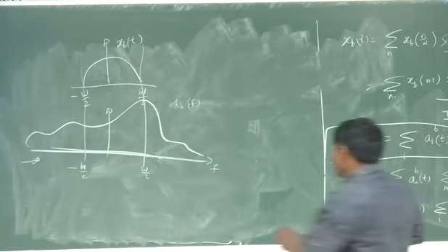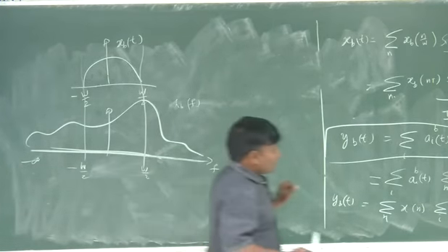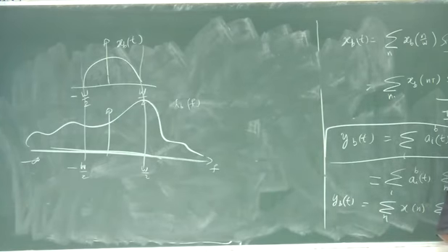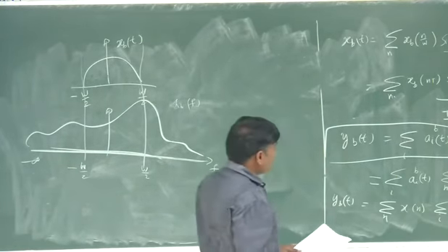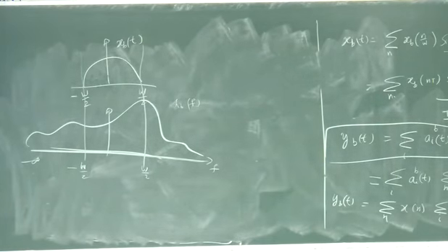Therefore, whether you have this or not, this only limits the noise. Okay. So what we will do is, we'll assume that this filter is not going to alter the characteristics of the received signal y, because we are considering the noiseless case. Yb of t, input is also Yb of t, and at this point we take samples at the rate t equal to m capital T, where capital T is equal to 1 over W.